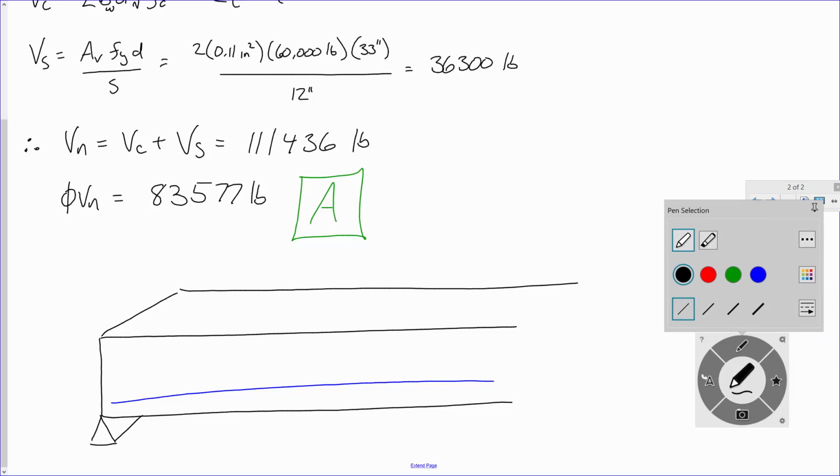And then on top of that beam, I've got some load, whatever, right? I am assuming, remember, that those cracks occur at around a 45-degree angle, so it's going to crack about something like that.